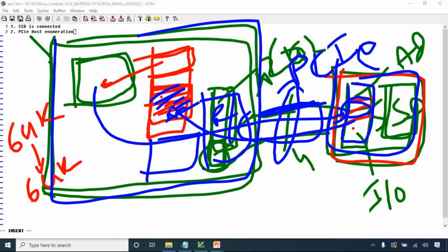Just one very related discussion. You are saying the host is going to write the configuration space, right? Yes. But what is the need of it? Typically on PCI, if I know correctly, usually the configuration space is fully written, right? Mostly the BAR registers need to be written. There are the BAR 0, BAR 1 registers that need to be written. Once we get into the basics of enumeration, you will understand that the configuration header will have 2 types of spaces.